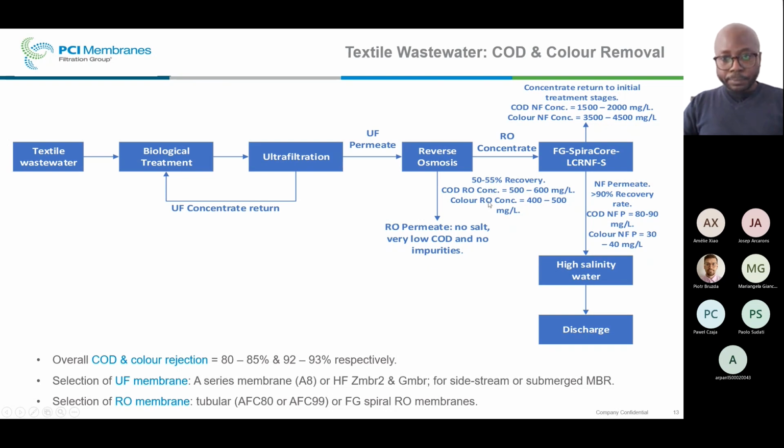And in the same instance, the COD in the concentrate of the reverse osmosis was in the region of 600 milligram per liter. And the color of the concentrate of the reverse osmosis was in the region of 500 milligram per liter. So these are specifications that are not acceptable for this particular client with regards to discharge.